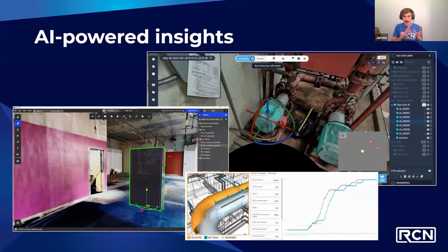Sometimes getting real time information might be the most important thing. I need to know if stuff is poured right now because concrete's going down, and if I need to move sleeves, I need to do it now before concrete goes there. I need to see where my PT cable is before it gets poured. Perfect. Great. But sometimes that's not the case.